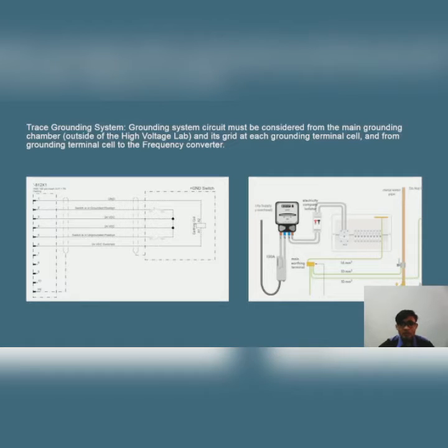And for the description, the ground switch switches to the grounded position when the software status is HV off or power off. It is always ungrounded when the software status is HV ready or HV on. Okay, for the precautions, first, always double check after switching off the high voltage part of the system that it is grounded correctly. And then beware, if the ground switch is in the grounded position, even the left part can be under voltage.